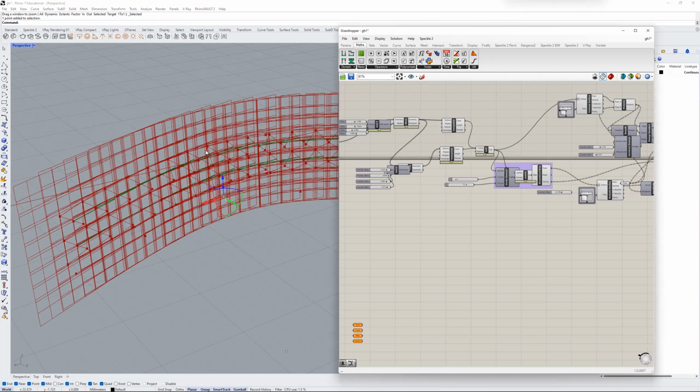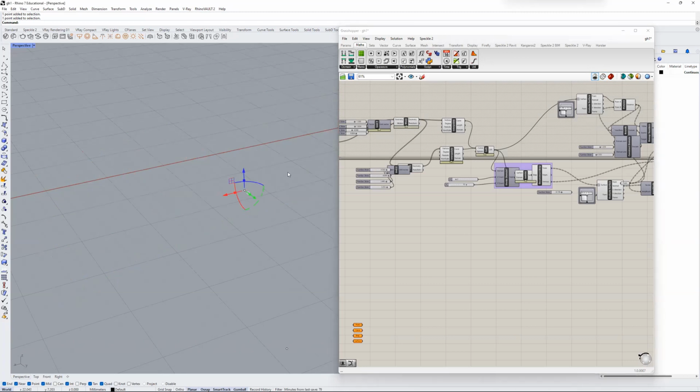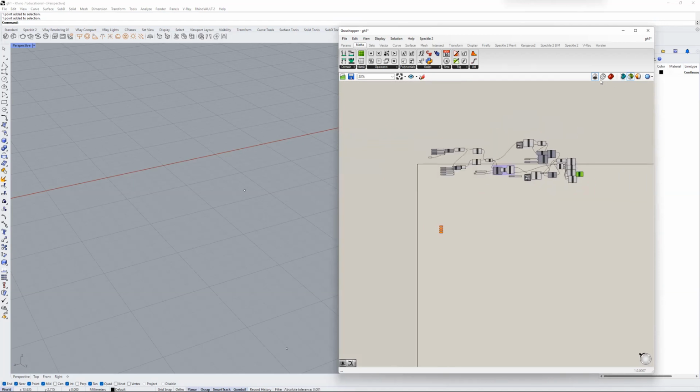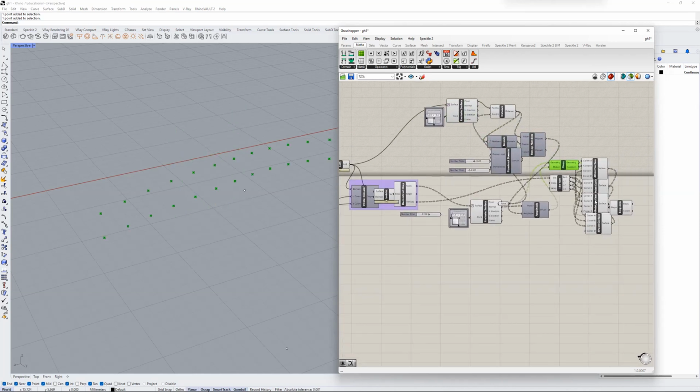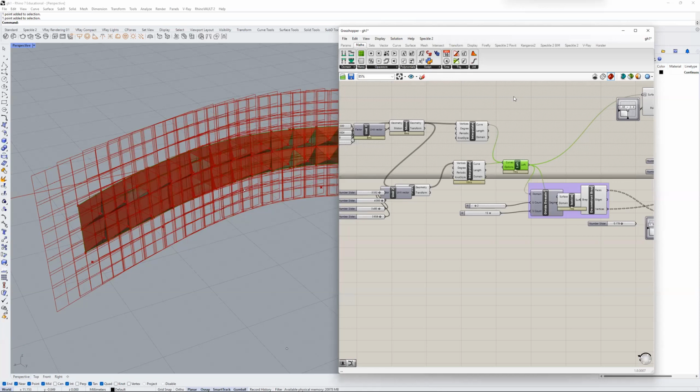You can also click this to wireframe everything. So you can still see, for example, this point here, it's hard to see now, but now I can clearly see it. There's also this green icon, and that will let you only render what you click on. If I click on this, I also have to have this set to the shaded geometry first. This just means that everything I'm seeing in Rhino and in Grasshopper will be visible in Rhino. Then with this green one selected, I can click on each of these components and it will draw only that component. So it's more clear to see. If I turn that off, it'll draw everything.